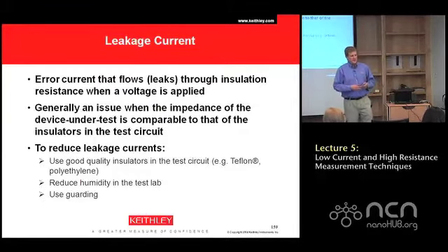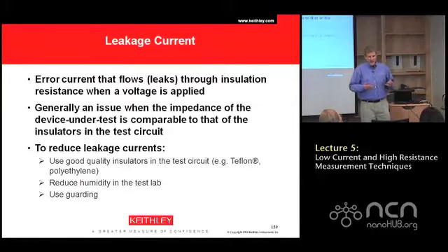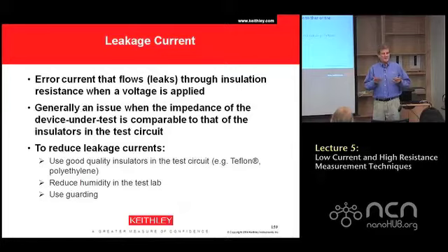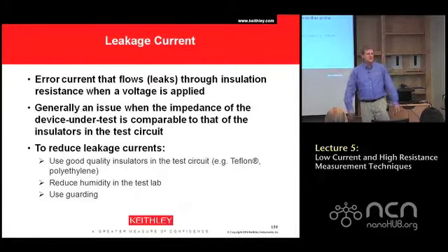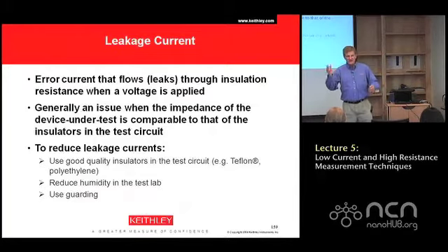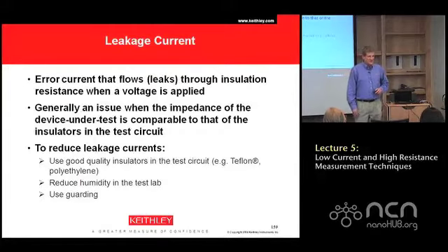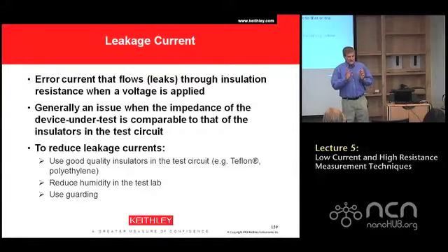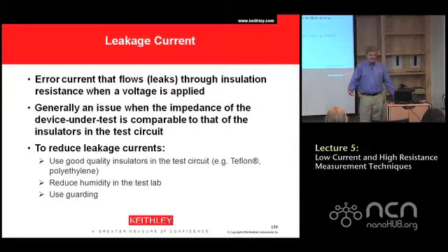And so, we happened to be paying a courtesy visit there, and we walked into the lab, and it's got to be at least 90 degrees Fahrenheit and probably 90% humidity, and all the windows are open in the lab because they didn't have an air conditioner in the lab. Okay, so the humidity is all over the place. Every connector, everything is contaminated with humidity, and who knows what else. All right, there was absolutely no way to make that instrument work. Every circuit board in the instrument was actually coated with moisture. Okay, it's a high impedance, low current instrument. Absolutely couldn't work. But they needed to get the measurements.